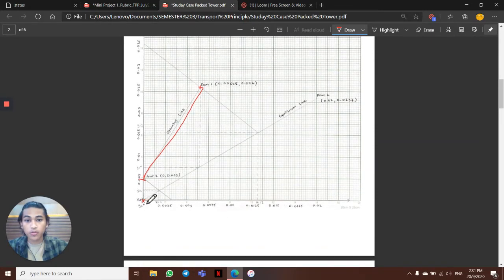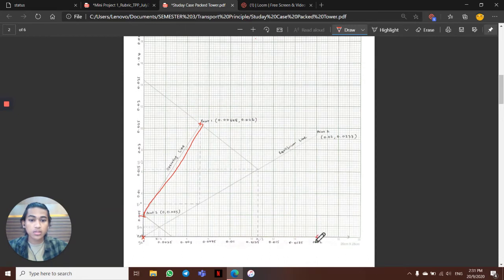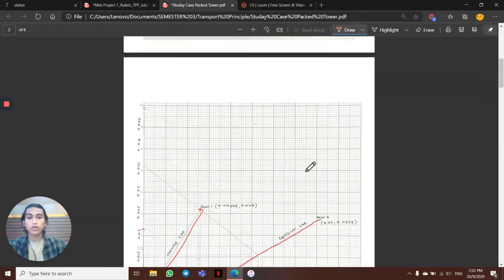For the first point, it is 0, 0, 0 for the equilibrium line, and insert the last number of your graph, which is 0.02 at the x-axis, and you can see the intersect of the y-axis, which is 0.0237. From this, we already have the operating line and equilibrium line. Alright,